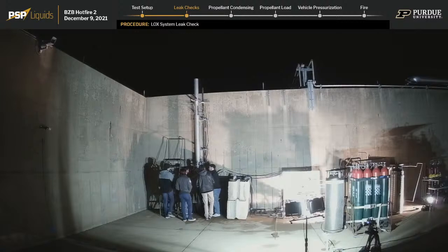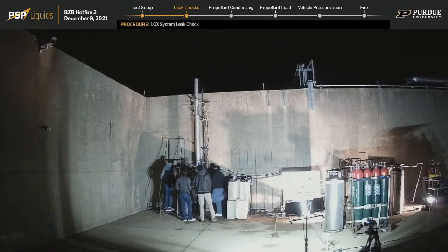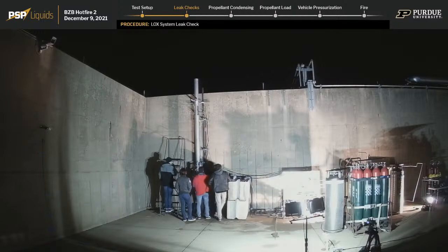There are a few things missing from this Hotfire, namely avionics are not on board right now, as well as quick disconnects. However, we are integrating those separately and have been doing integration tests of those. We just feel as if for this Hotfire they are not necessary and an added point of failure. In addition, the recovery system, nose cone, and fins are not present on this Hotfire test.